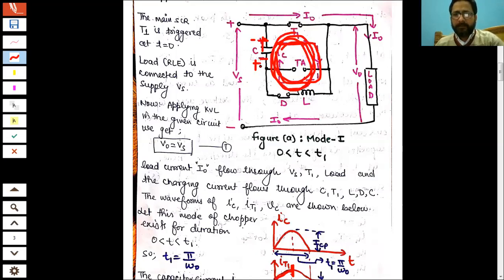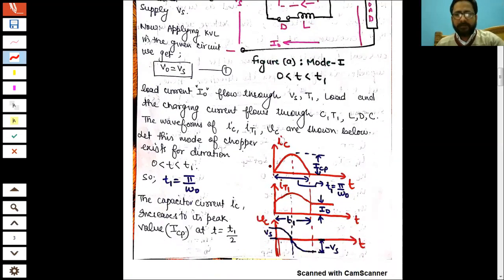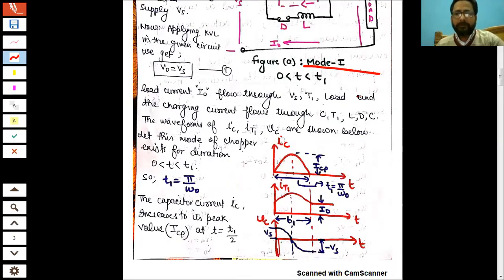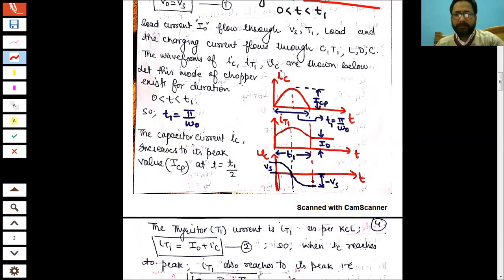अपर प्लेट लोअर प्लेट प्लस हो जाएगी, अपर प्लेट नेगेटिव हो जाएगी. वोल्टेज कितनी होगी? माइनस VC, यानी कि माइनस VS, राइट? माइनस VS. सो VC इज इक्वल टू माइनस VS. तो इसका मतलब ये है जब पूरा ड्यूरेशन मोड 1 खत्म होगा, एट द एंड ऑफ मोड 1 what will happen? Your capacitor is now charged with a reverse voltage which is minus VS, right?